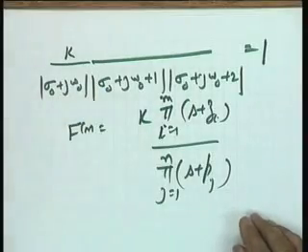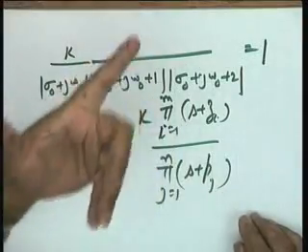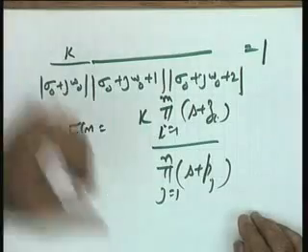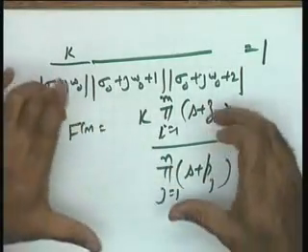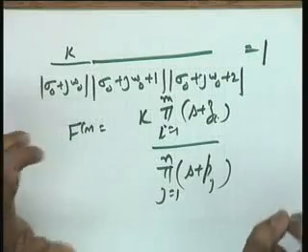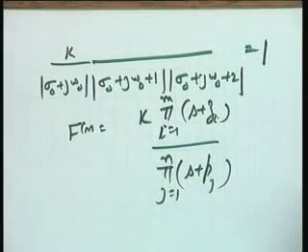Yes, please. All points satisfying this magnitude condition would mean you are taking different values of k. Yes, a root locus plot simply means that k is a variable from 0 to infinity. Otherwise the plot will not come, it is only a point. If you take k as a single value, where is the question of a plot? The word plot becomes meaningless, because for a particular value of k you get only a number of roots equal to the order of the system.